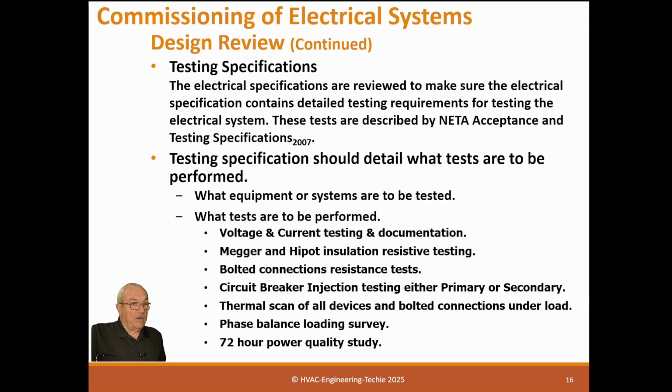A 72-hour power quality study. And this is what I like to see once the building is occupied and it's under normal load. We'll do a 72-hour power quality study to make sure we have no power quality issues at all. And to do that, you have to do it with a power study.